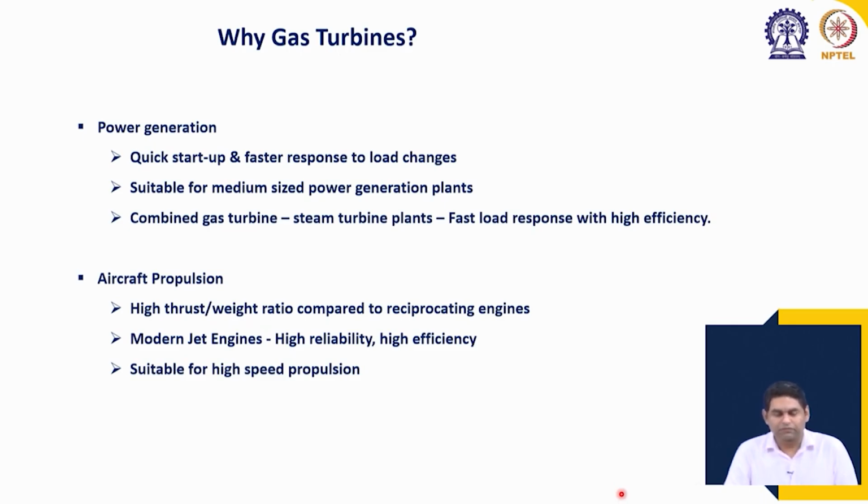Compared to steam-based thermal power plants, where steam is the working fluid, gas turbines have much faster response and startup time, which I have already explained. In gas turbines, the air comes in, gets combusted and goes out, a very simple process. In steam turbines, the steam has to be generated; it takes a lot of time to start the furnace, to get it up to a specific temperature, and then to generate the required quantity of steam continuously, then run the turbine. But those are efficient at very large scales.